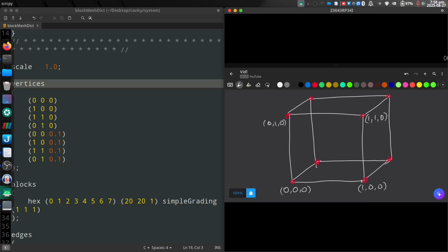All right, and then I decide that okay, I go by assigning it simply 0.1 as a thickness. Doesn't matter, you can give it anything, because front and rear face we are going to define as empty, so it doesn't matter what thickness you end up giving and what number of divisions you give there. It's simply going to be always 1, doesn't matter. So here I give it 0.1 for now.